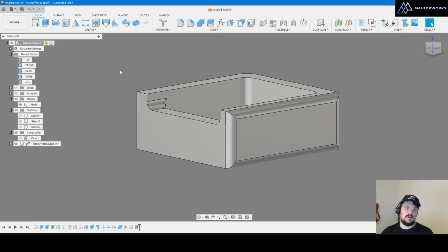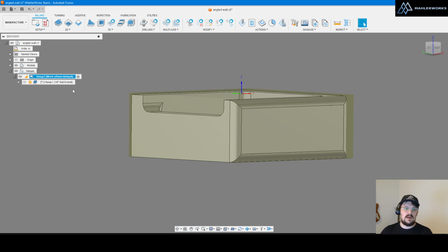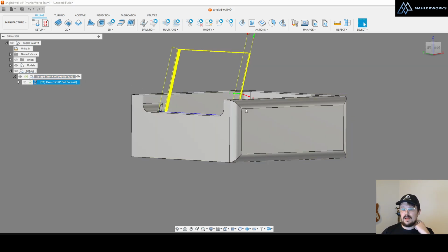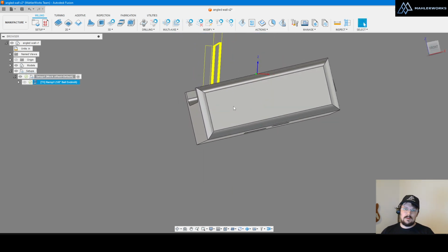And the other nice reason to change it to a darker color, and this is one of the reasons I use most often, is for double checking, especially on a CNC router situation, checking that my no tool paths are going down past my part into the table.